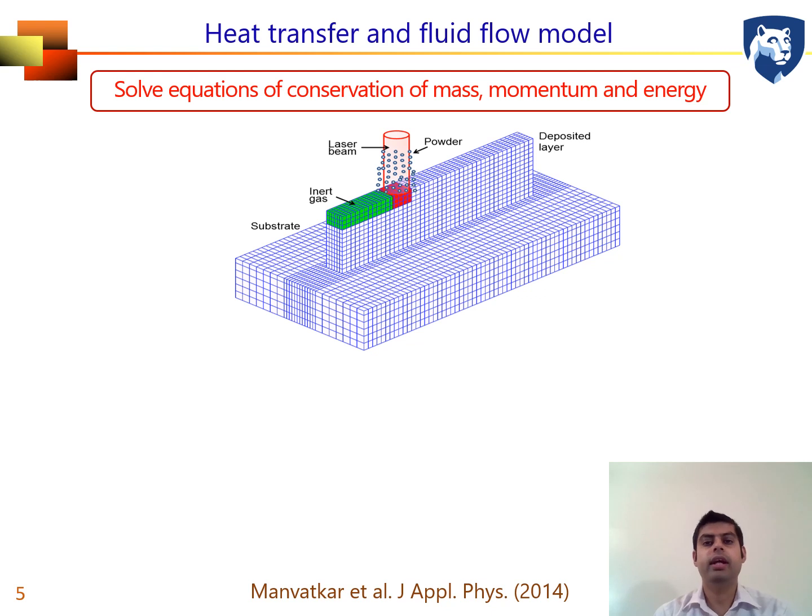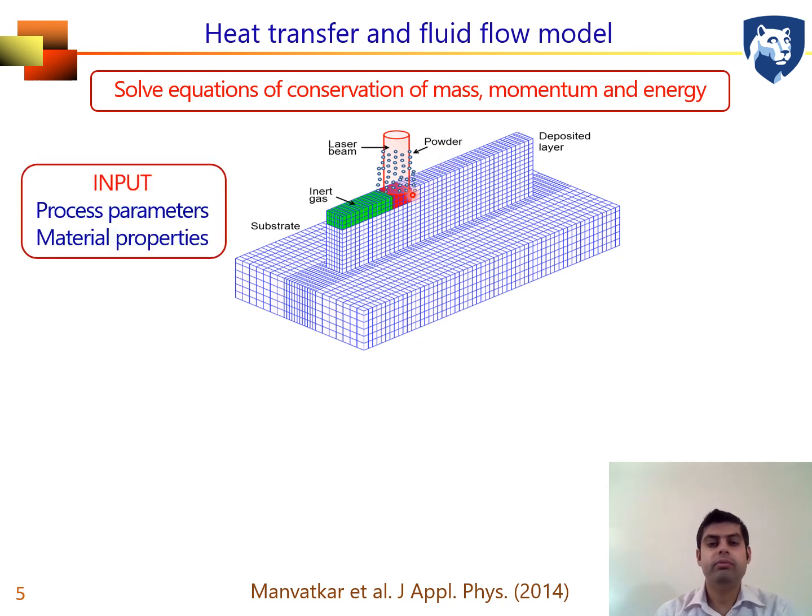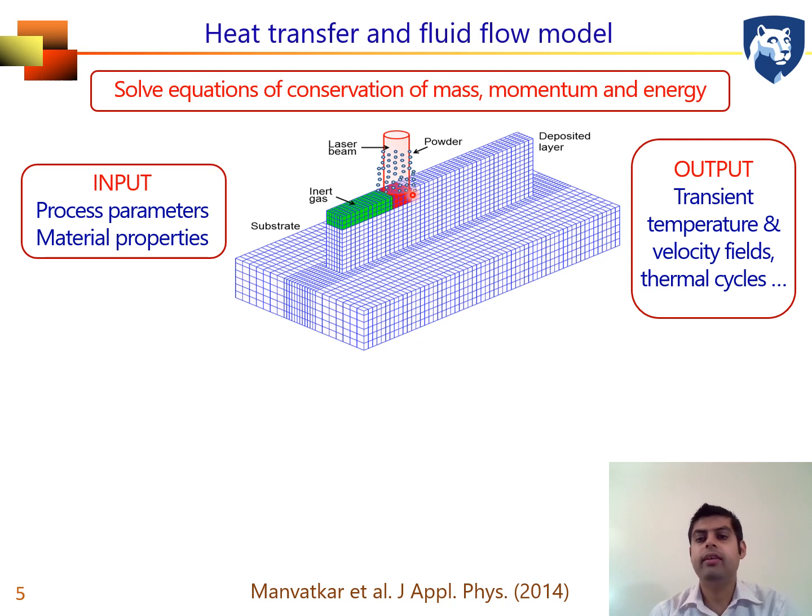Specifically, we use a heat transfer and fluid flow model that solves equations of conservation of mass, momentum, and energy in a 3D computational domain that consists of the substrate, deposited layer, powder, and the inert gas surrounding it. This model considers process parameters and alloy properties as input, and it provides us transient temperature, velocity fields, thermal cycle, cooling rates, and solidification parameters as outputs.